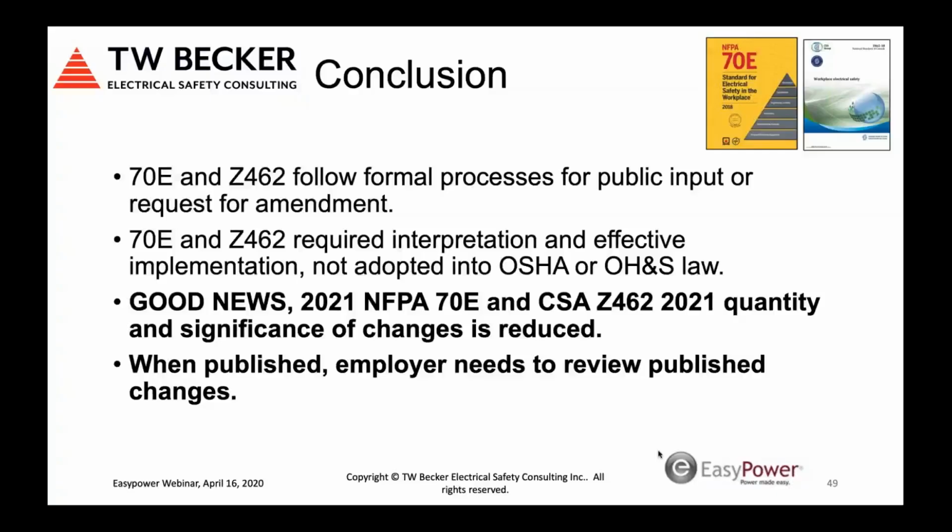Again, energized work, we will not be able to eliminate it. We need to isolate electrical equipment, test for absence of voltage. We need to do diagnosis and troubleshooting. We want to get rid of energized repair and alteration, if at all possible. As I said, the good news is that in the 2021 editions, the quantity of significant changes is substantially reduced.